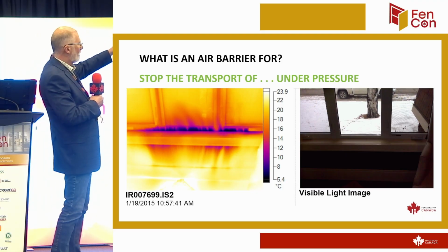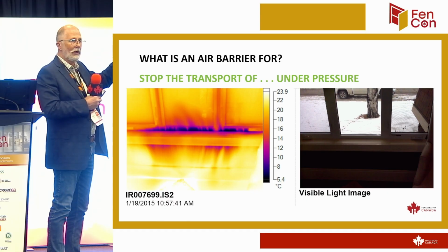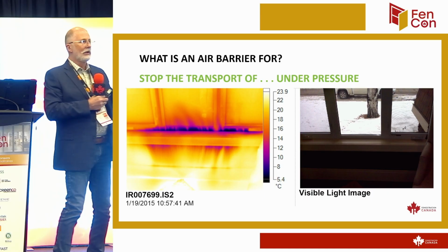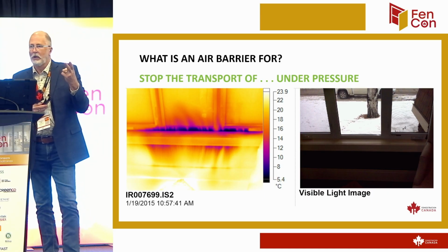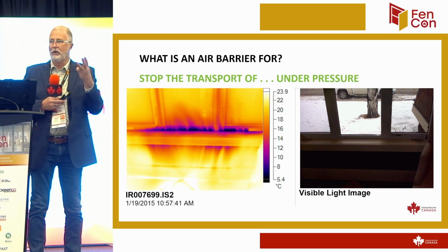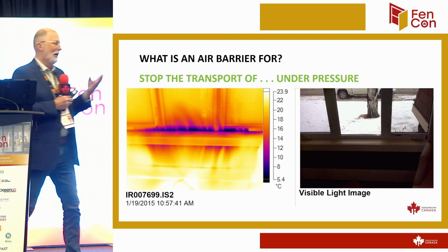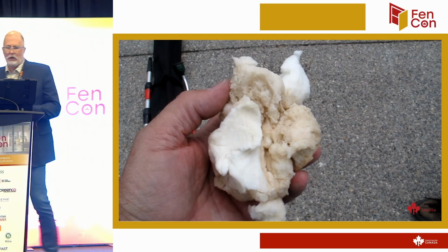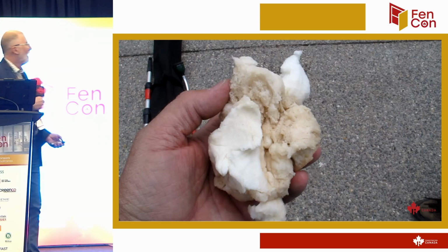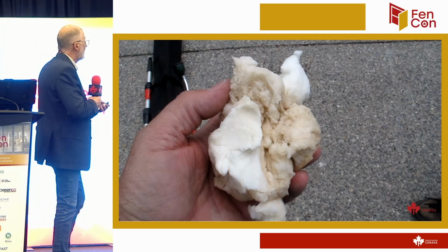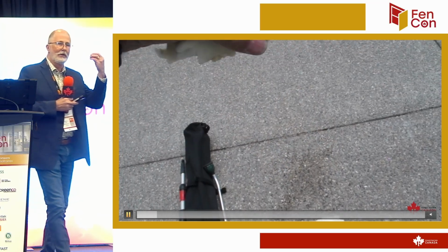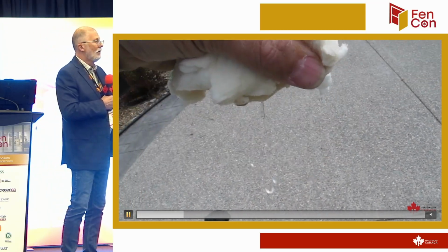What about in the summertime? If the rain is beating down on the face of that window and the wind is blowing, it's just going to pull all that water right into the building. So it's not just about condensation at that cavity. It's not just about stopping the air at the cavity. It's the consequences if we don't stop the air at the cavity. So that's why that's important to think about. Some people talk about spray foam as being a great insulator, but also as a great way to keep water from coming in. Because the concept is, if the water doesn't come in, question?